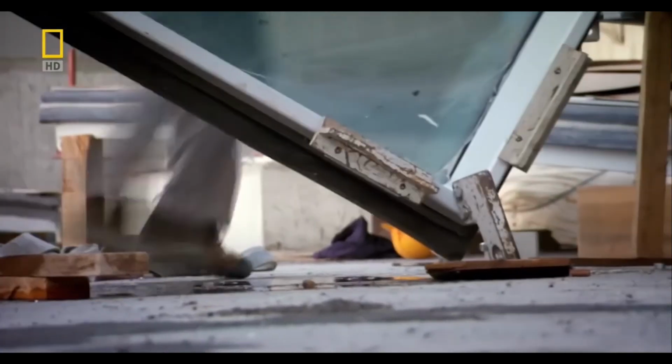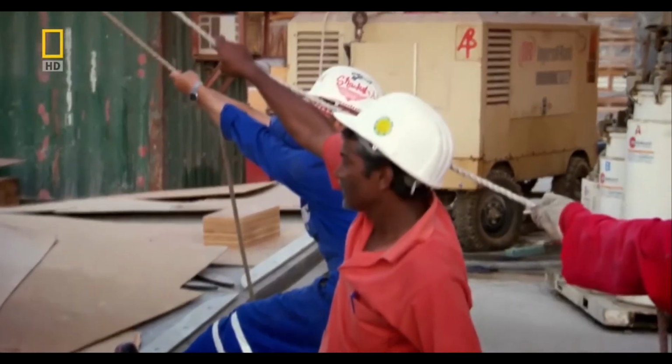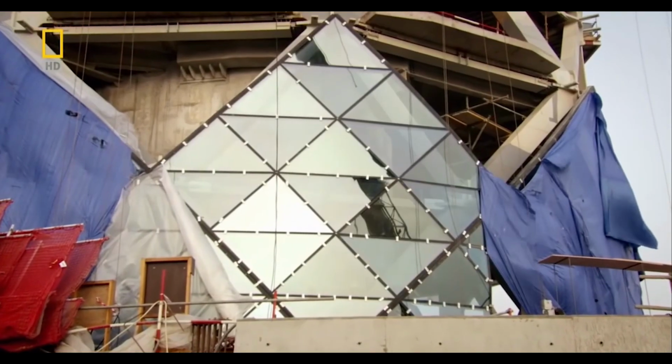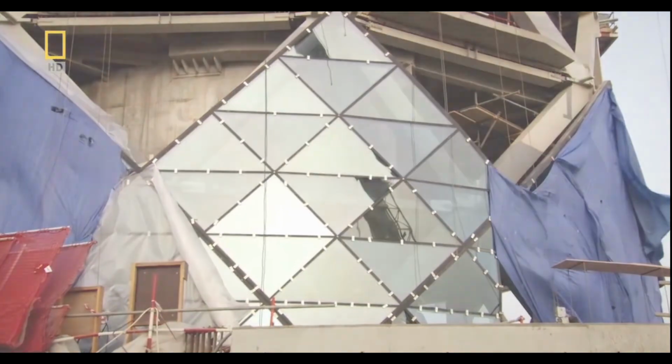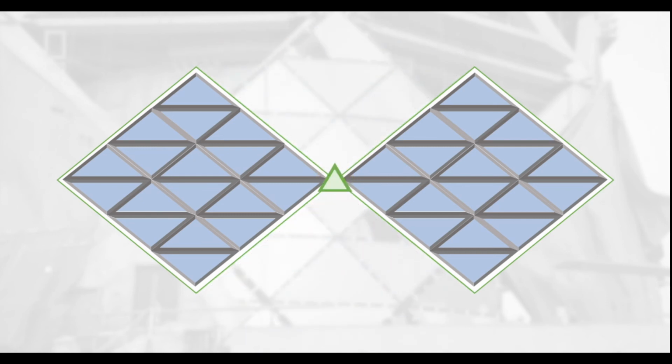With this difficult building, however, one problem is solved, the other is just around the corner. How did they cope with this unpredictable extra movement? Normally, as a diamond-shaped unit has 4 vertex points, it would be reasonable to fix all 4 points. Each point meets with 3 other diamonds, and so in total, each node gets fastened 4 times connected with each other. However, at Capital Gate, each large panel was fixed in just 2 places at each side.